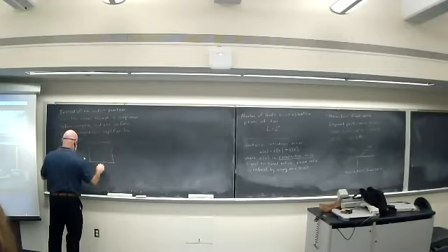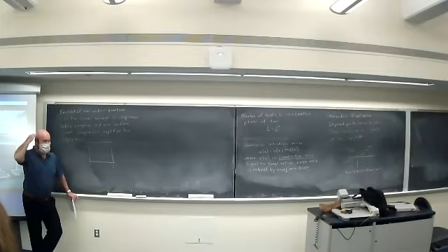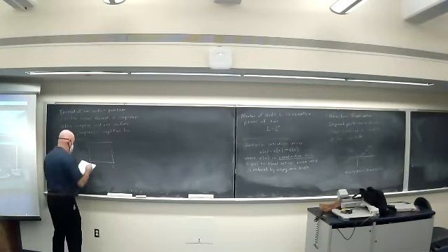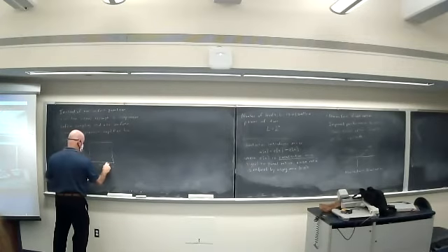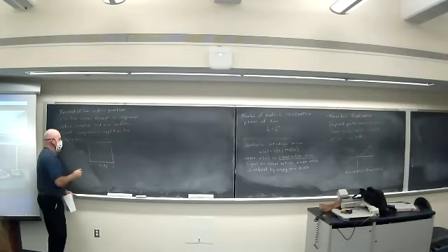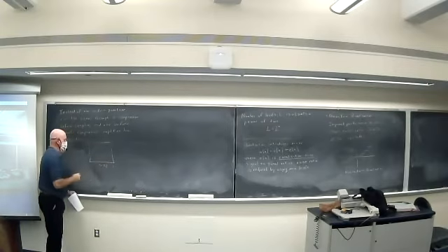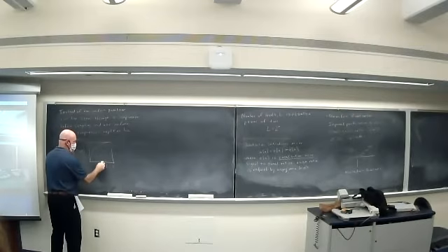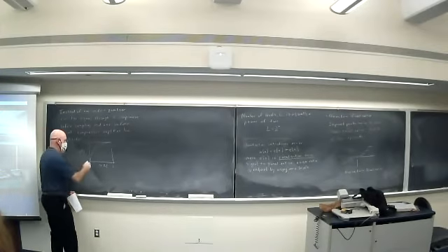So often we'll talk about our signals having normalized amplitude between -1 and 1. The negative portion of this curve would be the mirror image of this, but here is what a compressor curve would look like, something like this. For an input value of 1/2, that gets mapped to a much larger amplitude of maybe 0.75 there. So this is a typical compressor curve.